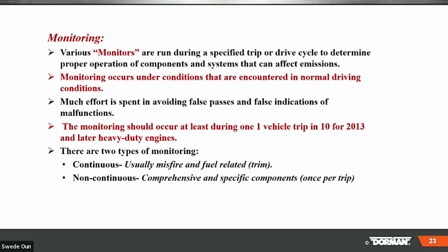But the bottom line is we're a little quick to hit that clear button and everything else. For years when I was doing a lot of automotive work, I would tell the guys: you do your repair, then drive the vehicle. Let the computer decide if that repair was proper, if it did the fix.